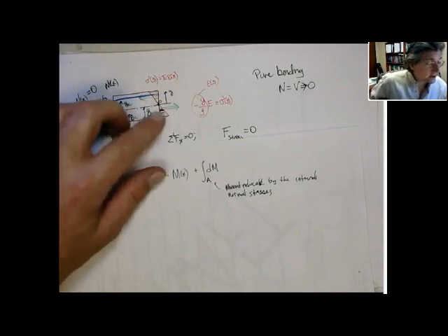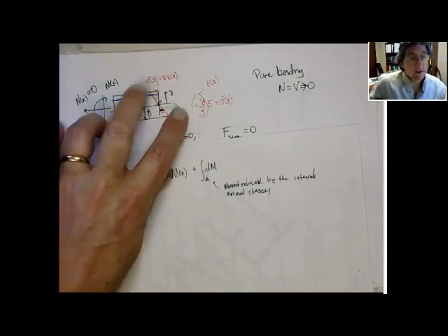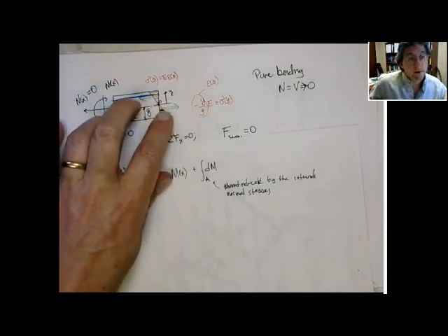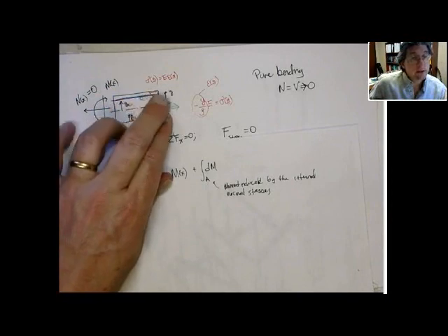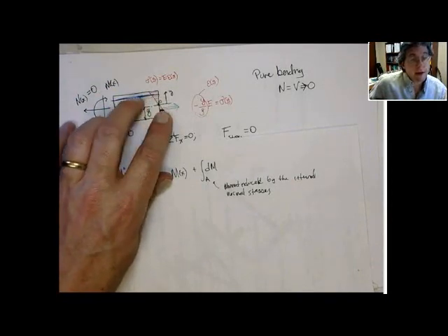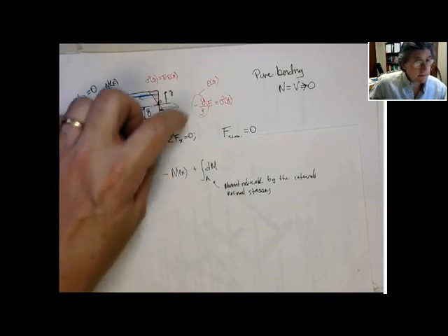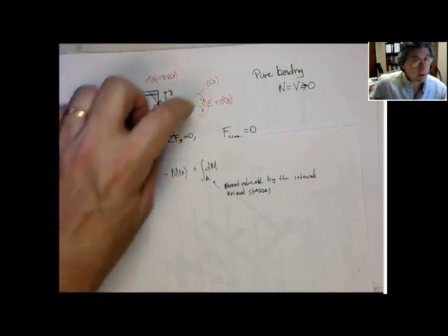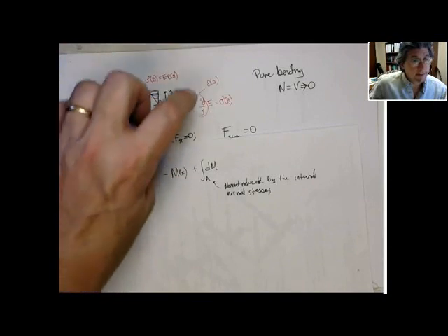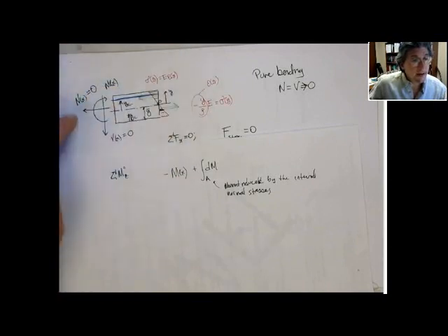So the tension stresses are going to act this way, through some point effectively below the neutral axis. Compressional stresses are going to act this way, in the negative x direction, above the neutral axis. And if you look at these two forces, you can see that produces a couple. And it's going to balance out the internal reaction moment.